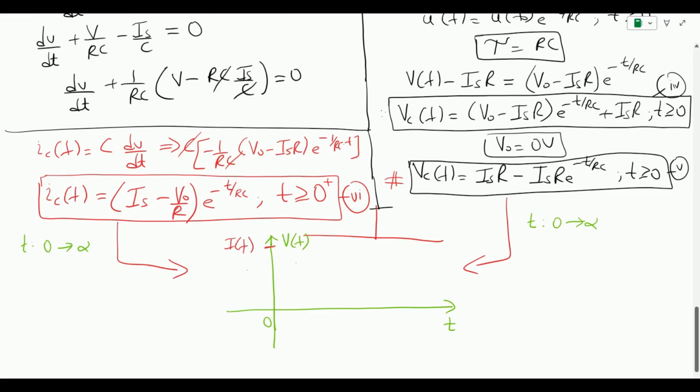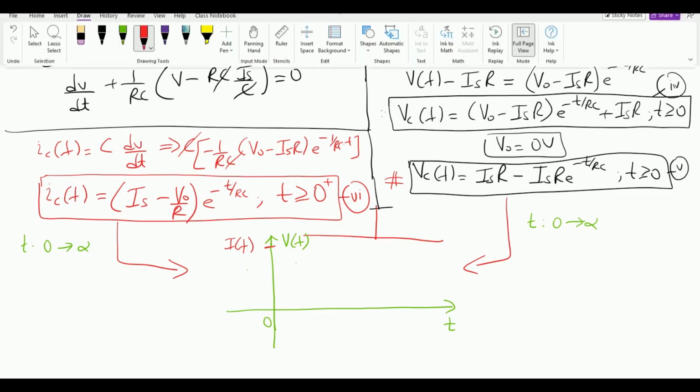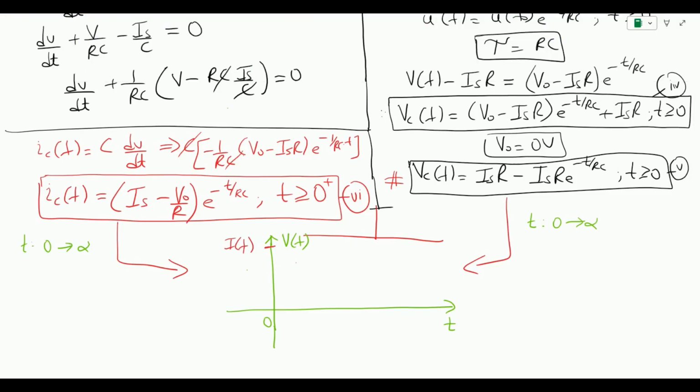So now if we plot the voltage behavior, we can see that at time t less than 0, and this is the time greater than or equal to 0. For t less than 0 everything remains 0 because the capacitor is not receiving any energy and it has already discharged its energy. So this is what we have before time equals 0.